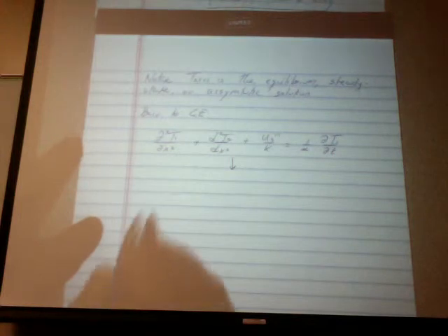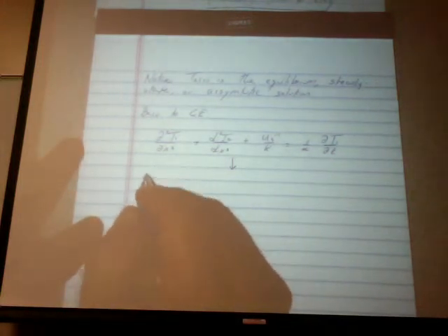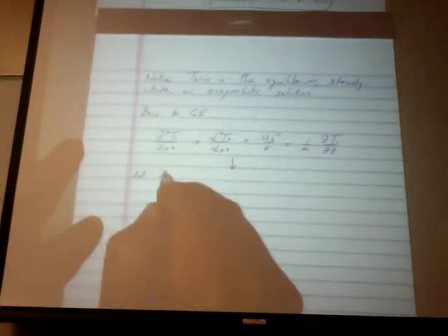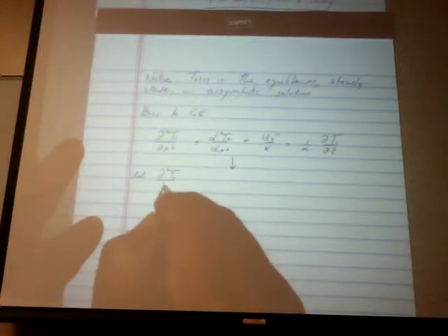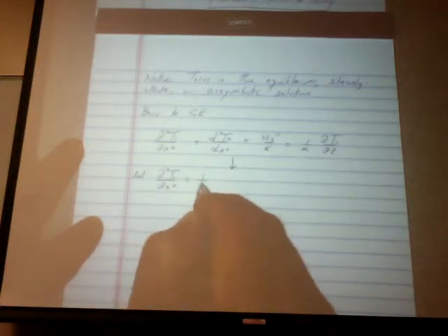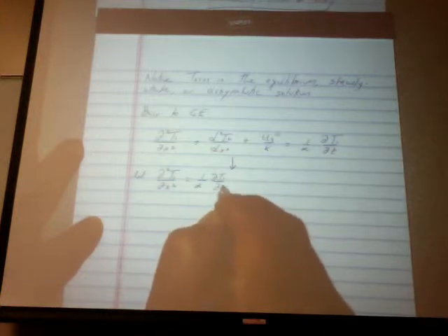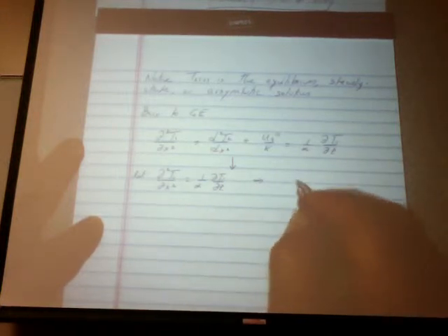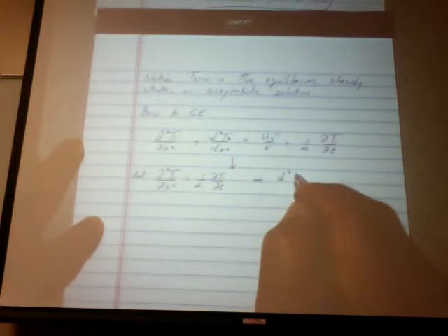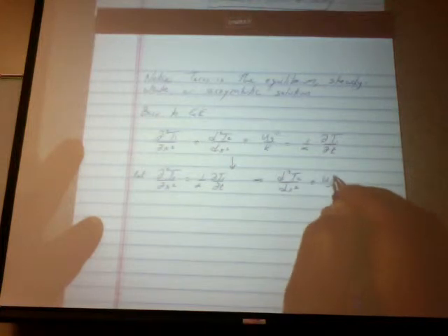And now we're going to separate: let the second derivative of T1 with respect to x squared equal 1 over alpha dT1/dt. And therefore, the second derivative of T2 with respect to x squared plus u_g triple prime over k is equal to 0. So we pass on the non-homogeneity, u_g triple prime over k, over to the steady solution.